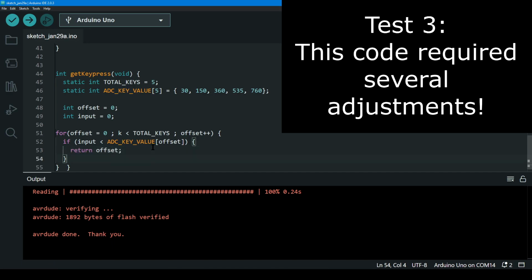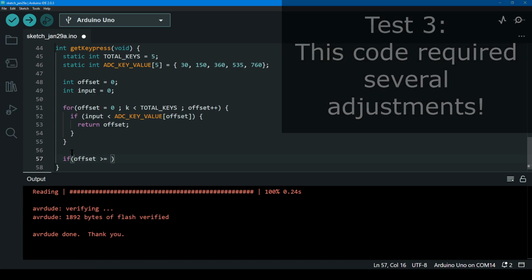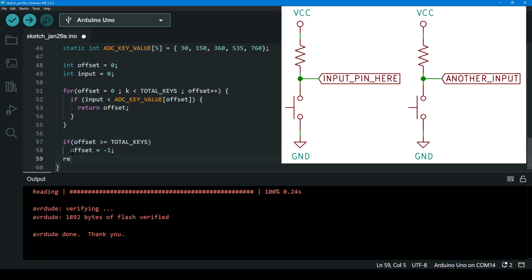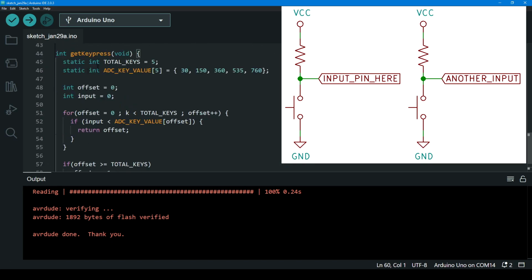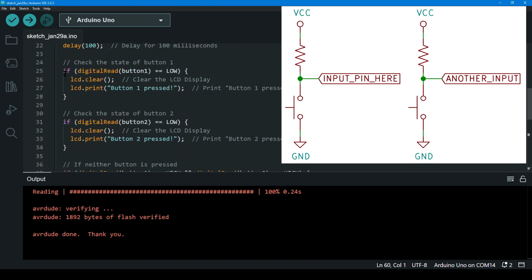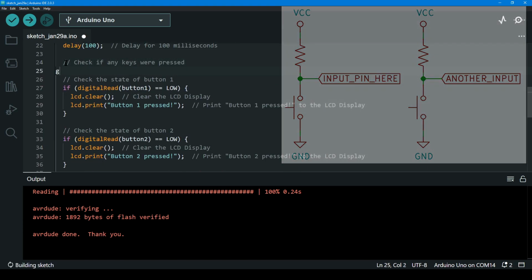With the third and final test, I was going to be a little bit more careful, so I checked the pin assignments against the drawing from the supplier, and I discovered that buttons 1 and 2 had been incorrectly assigned. ChatGPT had treated these 2 buttons as if they were regular tactile switches. Normally, a push button like this will pull the line either down to ground or up towards the supply voltage. It's a simple on-off operation.